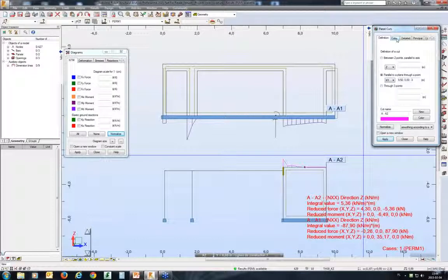Whether you want to transfer this wall to the RC wall design module, in such case you may, for example, create that as a single panel and, if necessary, increase the thickness of the edge part in the RC wall design module. So I'm afraid there's not going to be one simple answer for that. That depends on what your final objective really is.